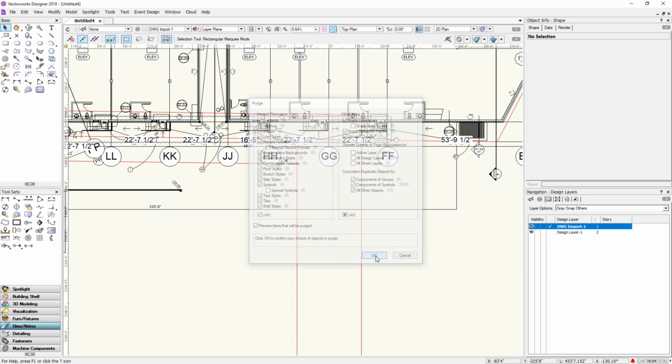To simplify our imported DWG or DXF file, we can use the visibility tool in the basic palette to hide elements of our imported file we don't need. To use this, select the visibility tool, then change the mode to Classes and Invisible Mode. If you hover over an object, all objects in that class will highlight in red, and clicking will hide all of the highlighted objects.